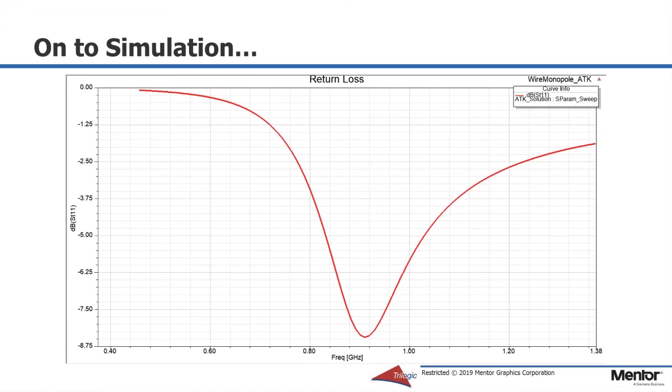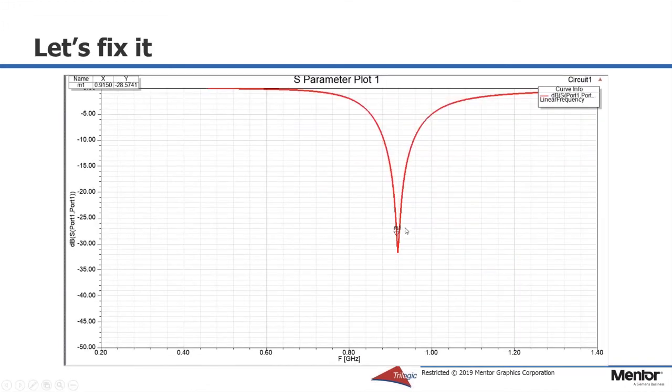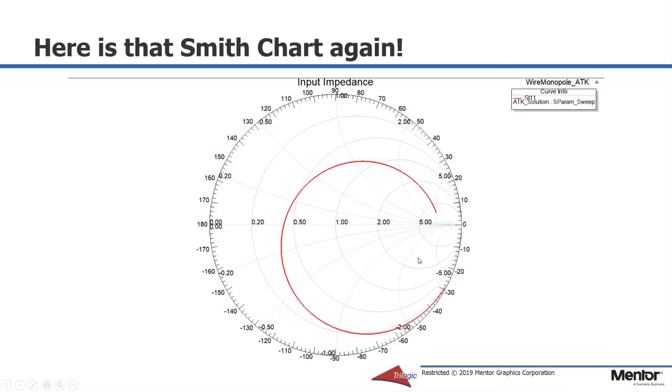And here we can see that we have an impedance mismatch because we have a lack of symmetry from right to left. So we introduced a marker that allows us to pick a frequency of interest for optimization right here. And here's that Smith chart again. The Smith chart tool is in several simulators, and it allows us to graphically introduce the network by adding capacitors and inductors by following this frequency line here.